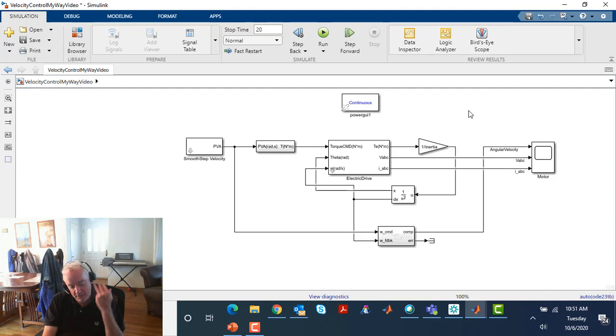But then the hardware folks also impose this additional thing that's very important: this is an algorithm, and it's an algorithm that has dynamics to it. What I mean by that is there is real mathematical calculus taking place, and you see that in the PIDs. What does I stand for? It stands for integration. What does D stand for? It stands for derivative. And that dynamics always has to be approximated on a computer.